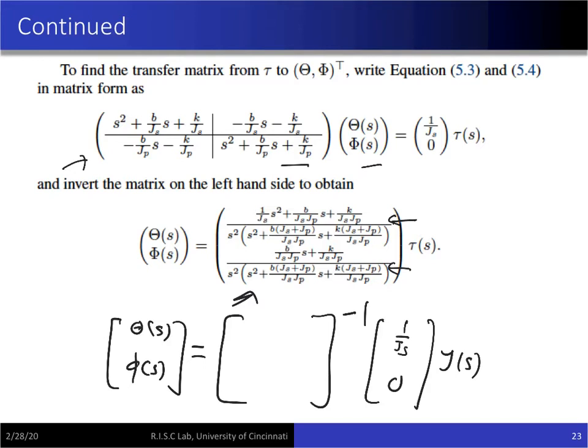Okay, and you will see that the characteristic equation, the denominator, in both the cases is the same. That also tells you that the poles for one system, it doesn't matter which transfer function you're talking about, are the same. That's why it's called the characteristic equation: the poles for all the transfer functions are the same, and you can exactly tell whether it is stable, not stable, or things like that. Okay, but there are two transfer functions, right? So two fourth order transfer functions.